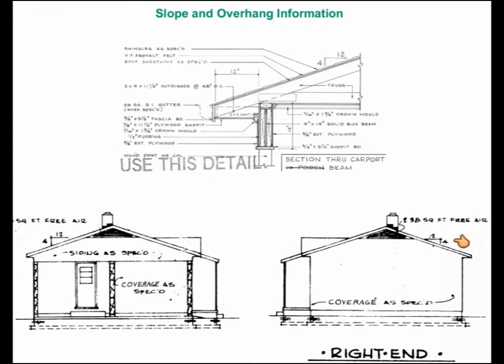After identifying the sides of the roof that slope, we will also need to put in the slope dimension. The slope dimension can be found in the right elevation as well as in the left elevation. It can also be found in the eave detail. The slope of the roof for this project will be 4/12.